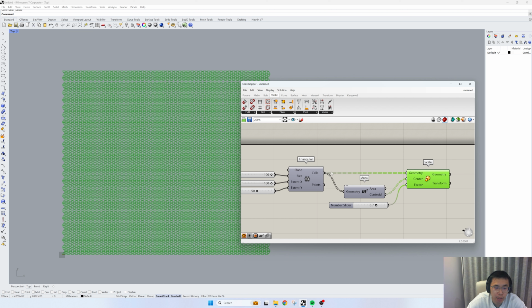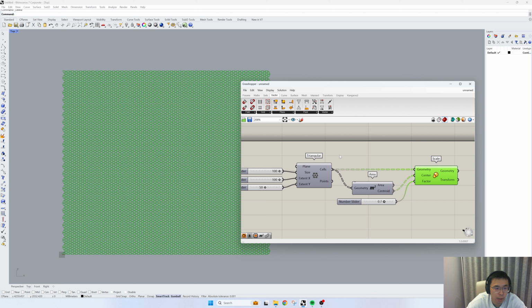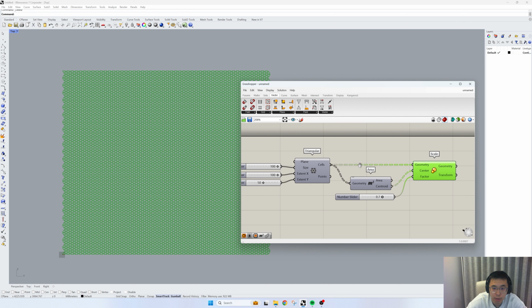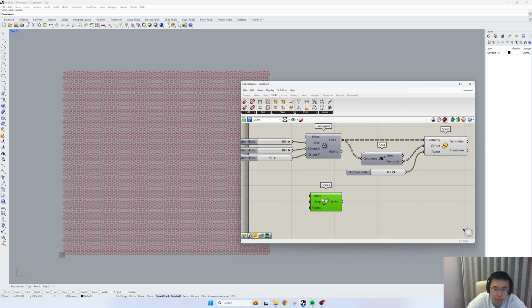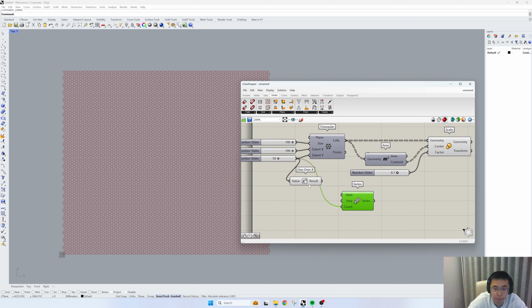And then we can use the method that we introduced in tutorial 1 to create consistent changing patterns from bottom to top. So I'll just quickly run it here. If you want to understand the logic in it, please listen to tutorial 1. Then we connect that 50 to Count. We can use 1 to divide the count, and then use Minus, then we minus 1.